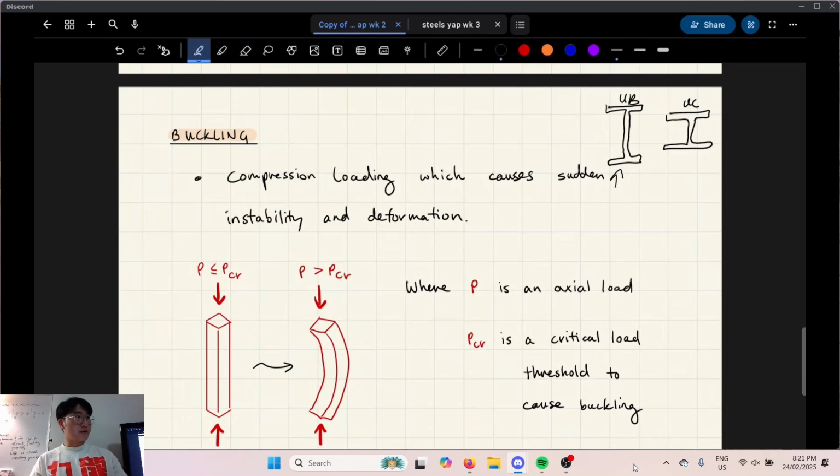Pretty much. Because on the universal beam, you're applying a load from the top. When you apply a load from the top, in this case our major axis would be the vertical one, so it would be stronger that way. Usually you call the XX axis the major axis, and this one's the minor axis. So bending, like the way that I showed you, where it was kind of buckling, that's really weak for beams.